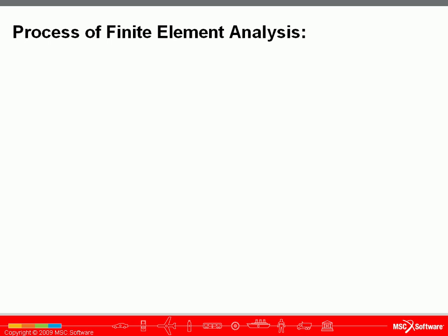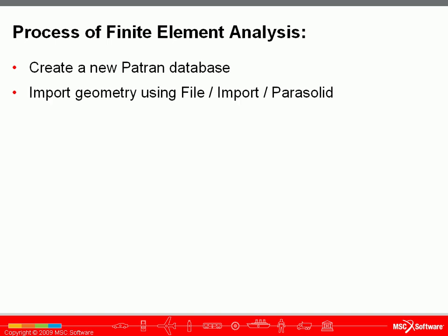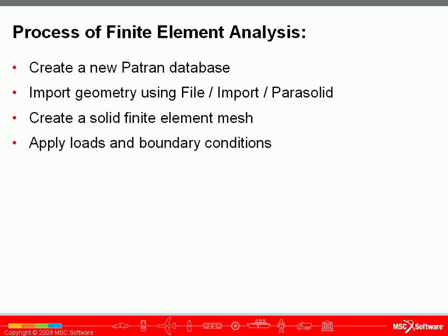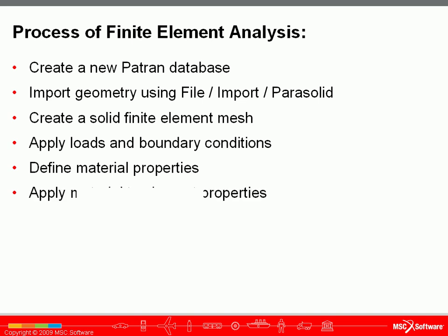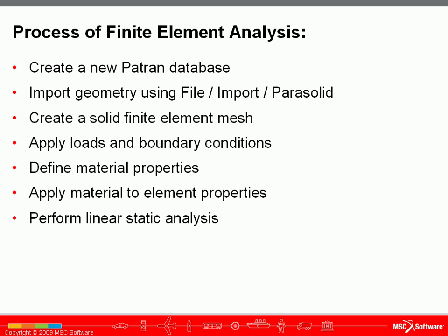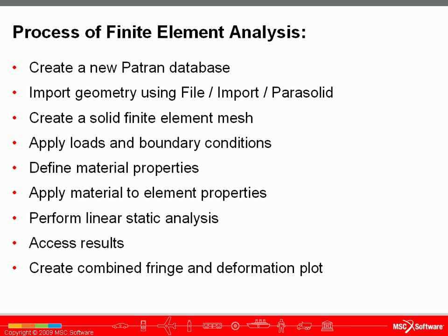The basic process that we'll show for a finite element analysis is, first we'll create a new Patran database, then we'll import geometry using File, Import, Parasolid. We'll create a solid finite element mesh using this parasolid geometry. We'll then apply our loads and boundary conditions. We'll define material properties, and then apply those material properties to our elements with element properties. We'll then perform a linear static analysis using MD Nastran. We'll access our results via an XDB file, and then create a combined fringe and deformation plot using Patran.